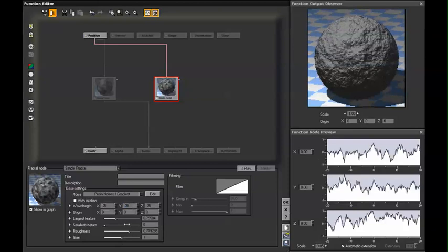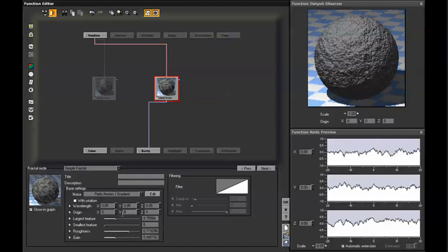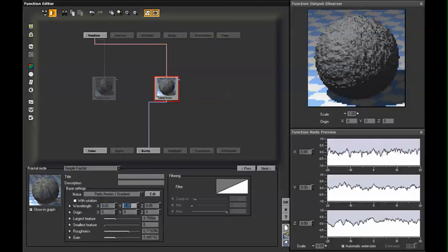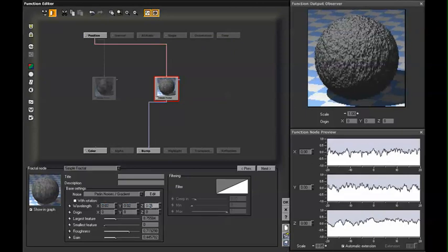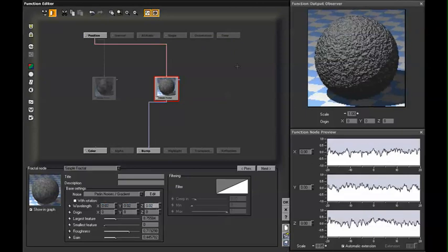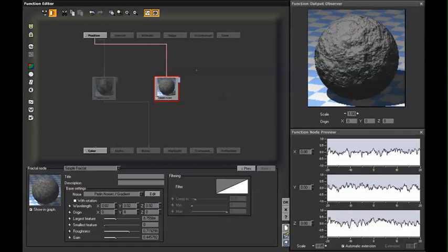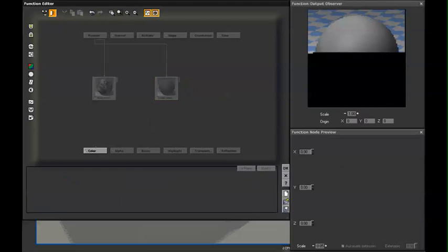Increase that roughness. And now we're not seeing that effect because our connection is on our other fractal. So we can move that over, decrease our gain a little, and I'm also going to decrease that wavelength a little bit more, replacing our 5s with 2s so that we have 0.02 all the way across. So now we have two different types of fractals, one that's a little bit smaller, with tighter variations, and then one with larger. So we can delete that link to our bump.